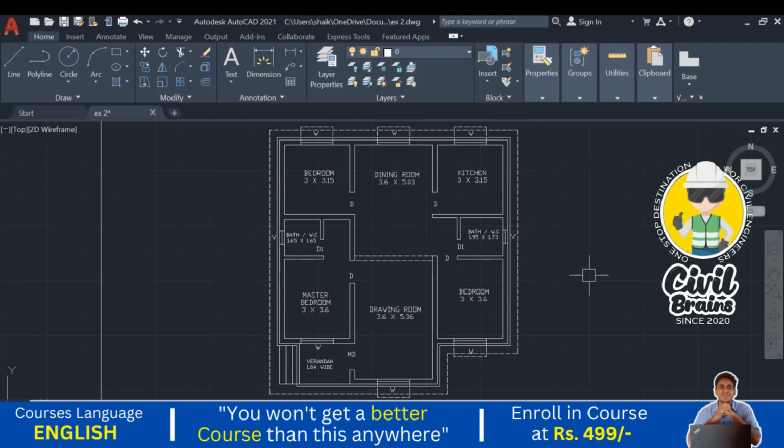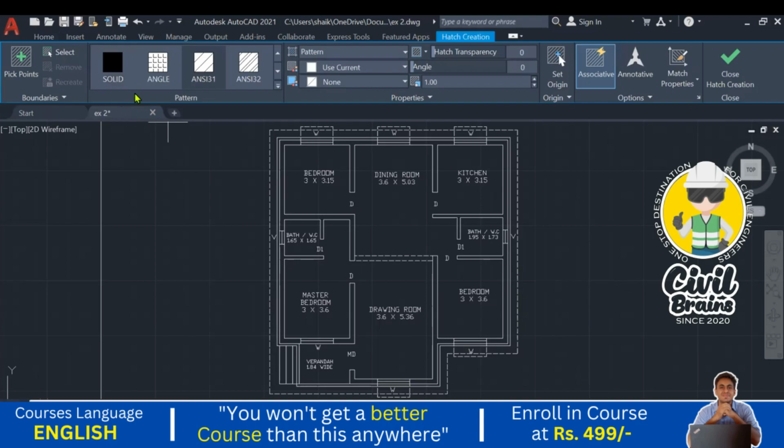But once we hatch that one, the plan will be finished, and we need to show the section line also. Okay, plan means finish, and section line also we need to show. Okay, I just hatch that one. We'll see. If any difficulty comes, we delete the hatch and we can do that. Okay, I just go to the hatch command. Here you can see this one, hatch command. Click on the hatch command. Okay, so here you can see this one.